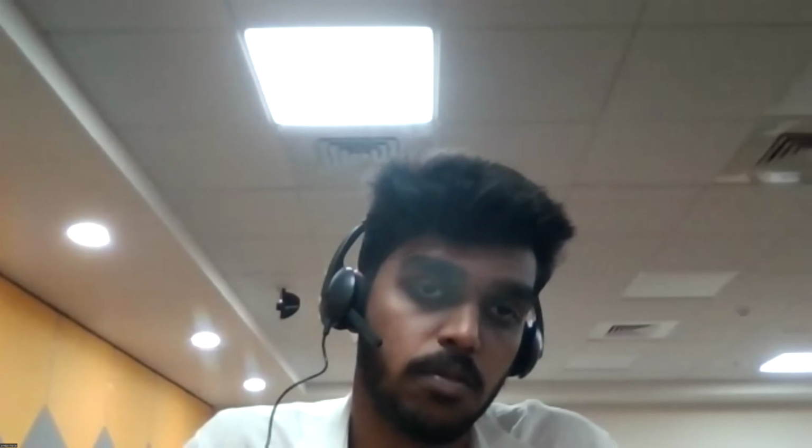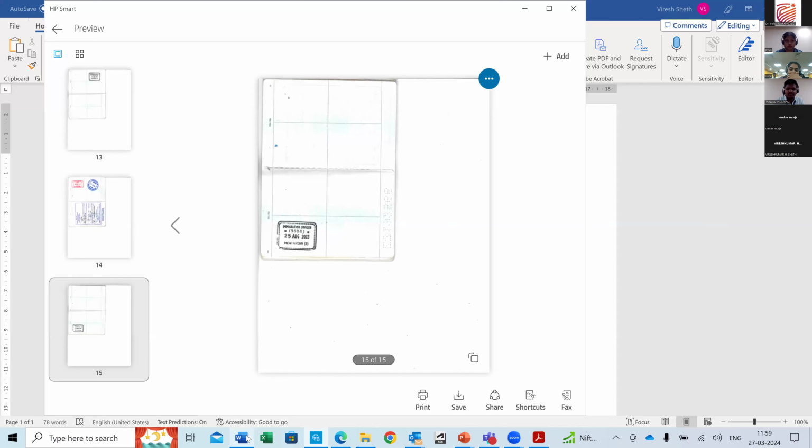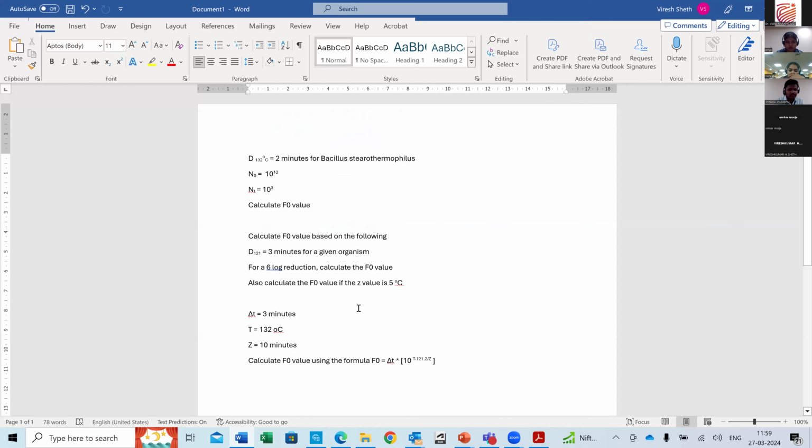Clear? Clear or not clear? Yes, sir. Cleared, sir. Now I'm going to share my screen and give you the third problem. Delta T is 3 minutes. T is 132 degrees centigrade. Z is 10 minutes. Calculate F0 using the formula F0 is equal to delta T into 10 to the power of T minus 121.2 divided by Z.